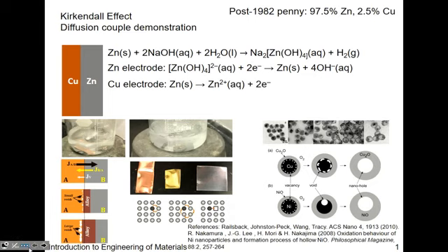Okay, so we'll talk about the Kirkendall effect, which is the diffusion of two metals together, or actually any particular system, but the famous 1942 publication by Kirkendall was based on this, which is the understanding of atoms and metals up until that point was that you have an interchange. One site, a metal A goes to metal B site, and then you have the flux going the other way. Okay, so that was the understanding, in that the rate of exchange was equal.